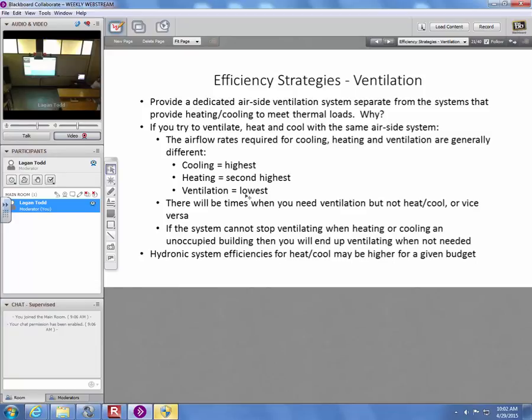You don't really need to move that other 1,940 CFM. See, and I did that for years. Yeah, a lot of people do. They'll go to the thermostat, turn the furnace blower on to fan only, just to get some air circulation. Absolutely. And you might have been doing it when there wasn't even any fresh air incorporated, because most residential furnaces don't have an outside air intake.